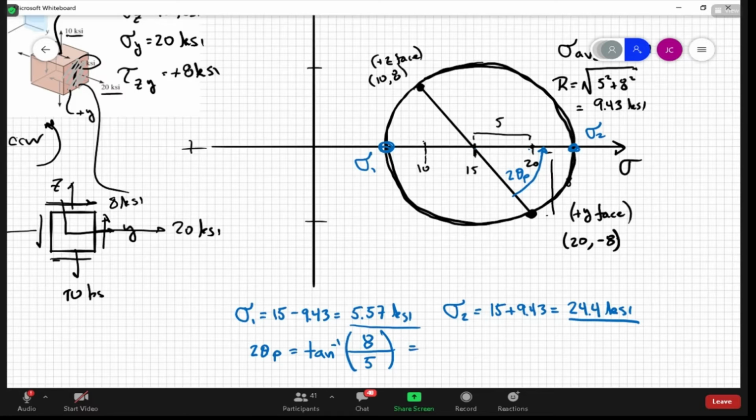You want to be careful about the quadrants, because whenever you take inverse tangent you could have 2 negative signs or 2 positive signs but get the same angle, so the quadrants could be off by 180. That's where the picture of Mohr's circle helps a bit.